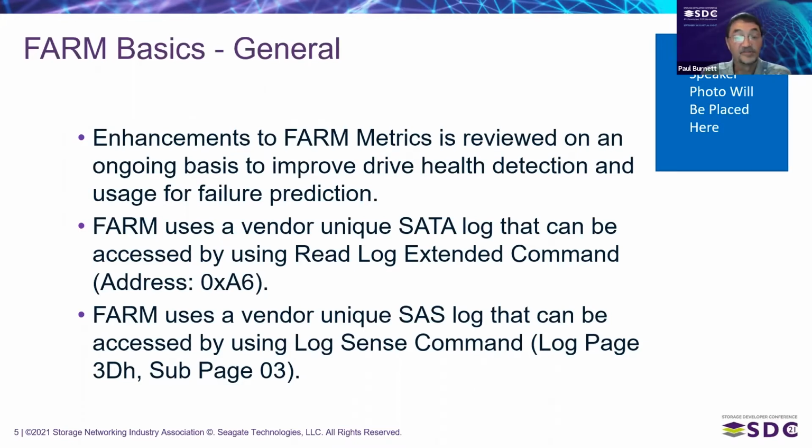FARM uses a vendor unique SMART log that can be accessed by the read log extended command, using address A6. For SAS, the FARM log can be accessed by the log sense command, which is a T10 standard, in log page 3D, subpage 3.